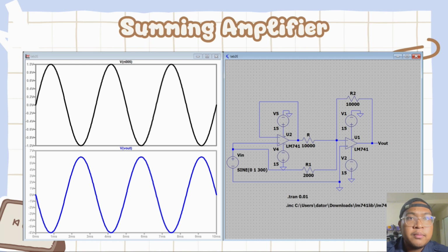However, we did observe minor deviations that are critical to analyze using principle-based reasoning. Firstly, the output amplitude in the inverting amplifier was slightly less than the calculated 10 volts peak. This is explained by the non-ideal characteristic of the output saturation voltage, where the op-amp cannot reach the full 15 volt supply rail. Secondly, the edges of the square wave from the Schmitt trigger were not perfectly vertical.